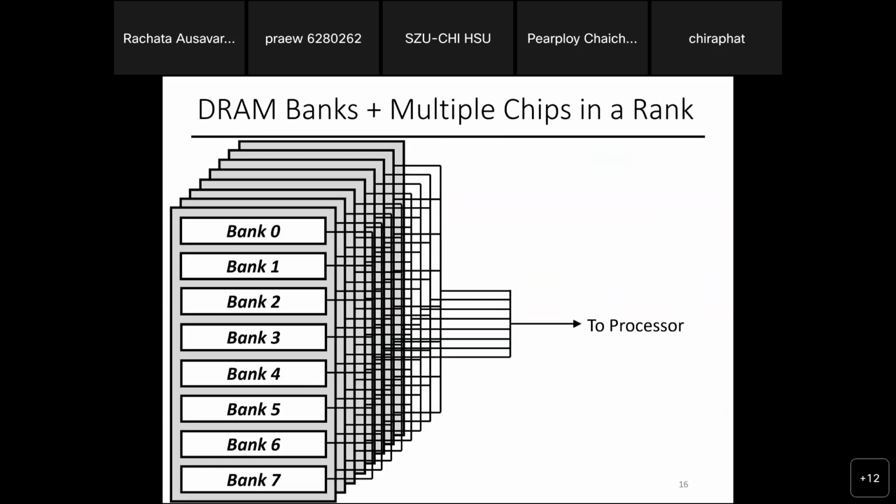So basically that's how it looks. In your DRAM, it's still 8 chips. They work together. That's why we named them a rank. Your access from the CPU is usually to a data word size, which is up to 8 bytes, right? But when you go to the cache, it operates in a cache block unit, which is 64 bytes. And when we have a cache miss, that's when you interface with DRAM. So DRAM should give you back 64 bytes, not 8 bytes.